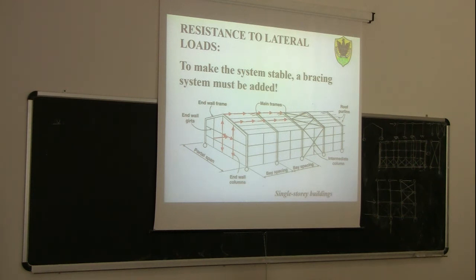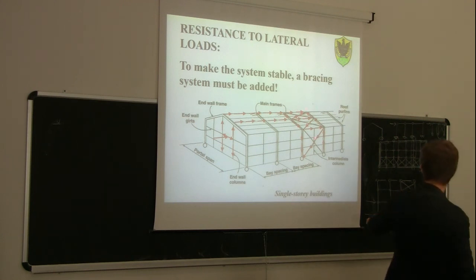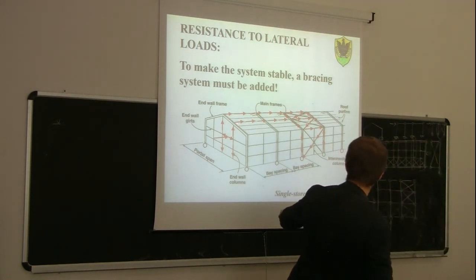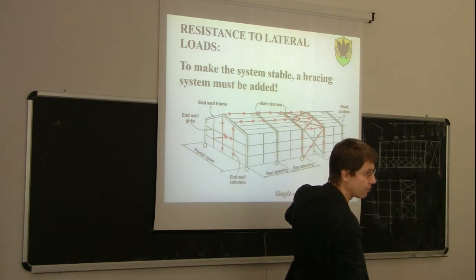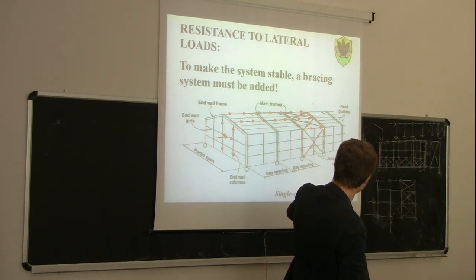And then, of course, from the bracing system, note also this is very important. So, the purlins will be subjected to axial force because of the wind, longitudinal wind. And as you can see here, then here we have a bracing system. Just what you are now, then I think we have to stop shortly.